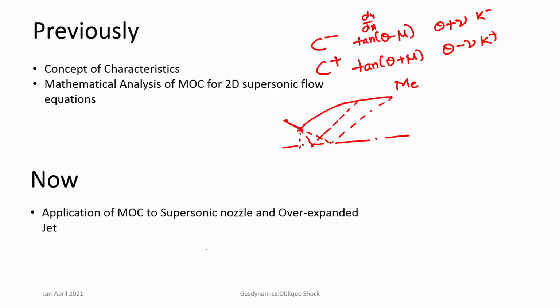I have to give a certain flow turn so that the flow expands here, that is theta wall maximum, the theta wall that I have to give in order to achieve a certain exit Mach number. This relationship was theta wall max is equal to the Prandtl-Meyer angle of the exit flow divided by 2. This we also proved by using the method of characteristics itself.